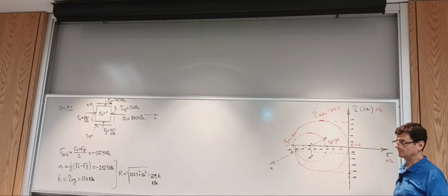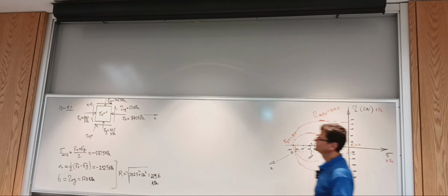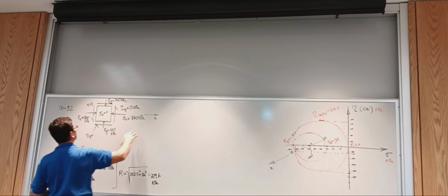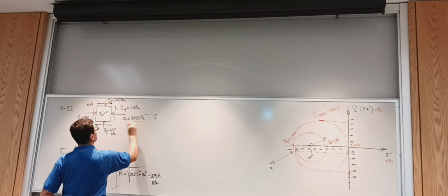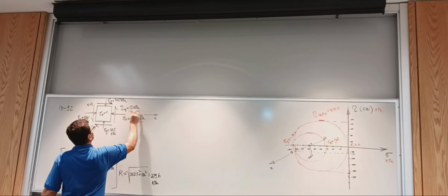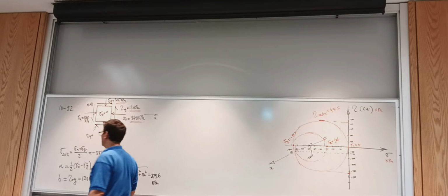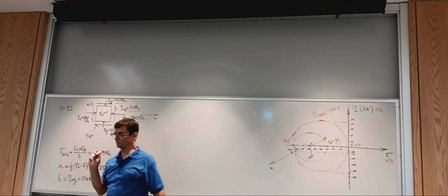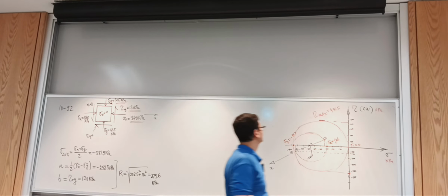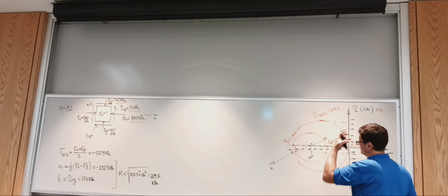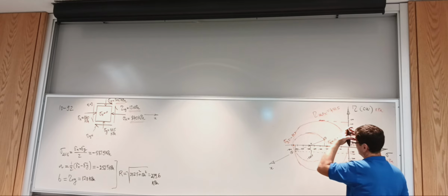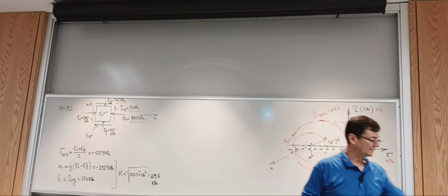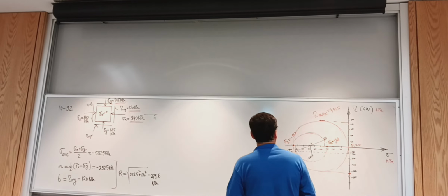Okay. A tensile stress, how can you do a tensile stress? Maybe by pulling. Again, these are numbers that were given to us. The more involved part, in my opinion, is always to figure out these actual stresses before you draw the circle and calculate tau max or sigma 1, sigma 2, and sigma 3. Okay, so now I have sigma 1, sigma 2, and sigma 3. I can draw the stress element, or the principal element.